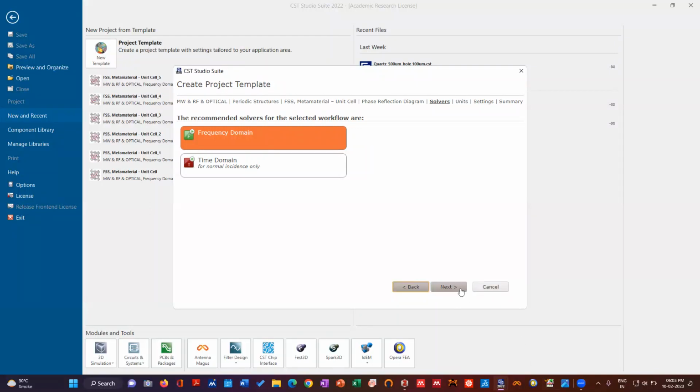The thing is, Floquet port, right? One minute, I will just show you this unit cell. What you were asking, what do you mean by Floquet port, sir? You have a unit cell like this. Then, for example, you will create a boundary like this. Then you have a planar wave getting incident on this. Then you will simulate, right?